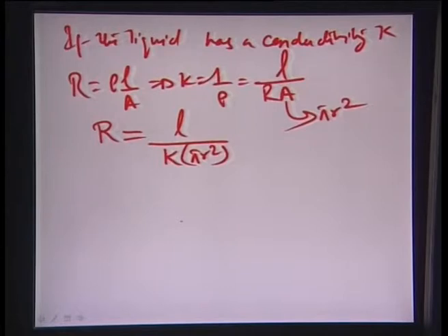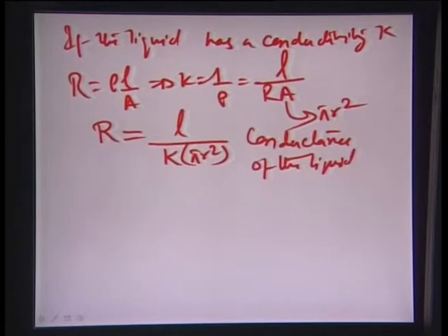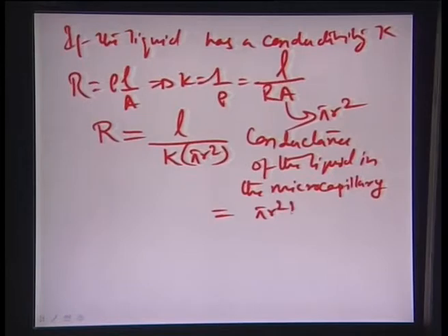In other words, the conductance, which is the reciprocal of resistance of the liquid in the microcapillary, is just the inverse of that, that is pi r square K by L.